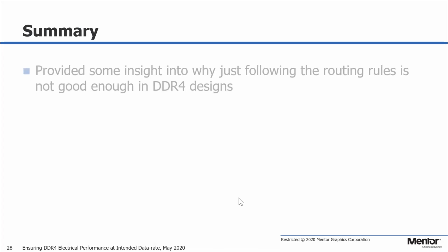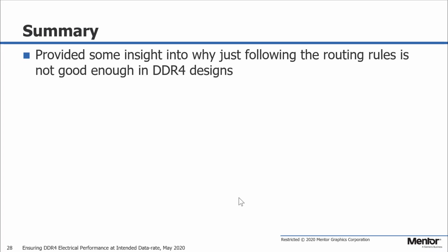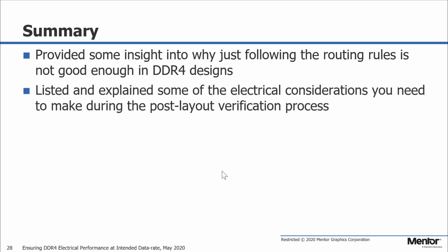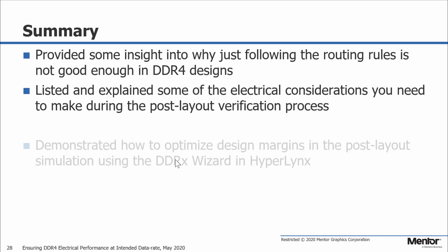So in summary, I provided some insight into why just following the routing rules is not good enough in DDR4 designs running at high data rates. I listed and explained some of the electrical considerations you need to make during the post-layout verification process to verify that you have plenty of timing and signal quality margins.